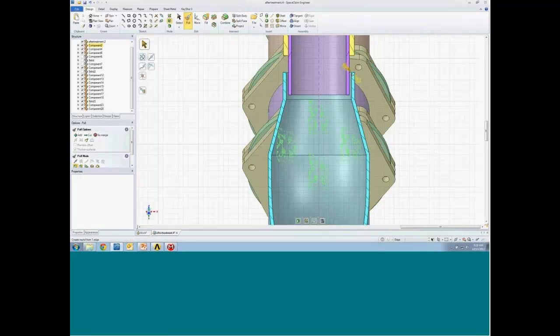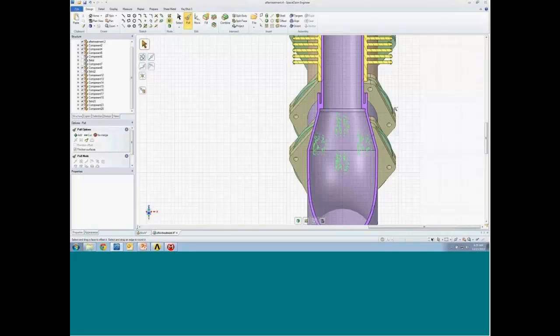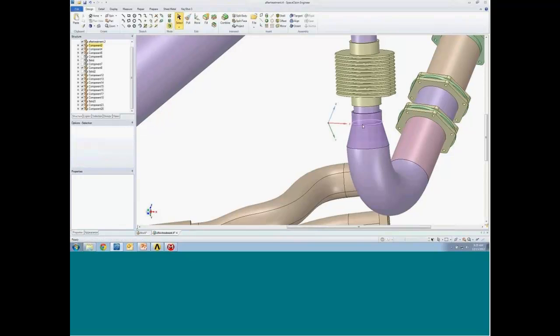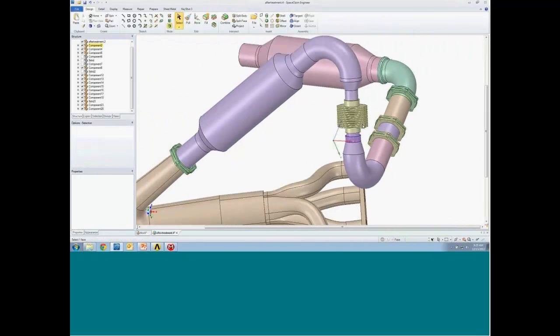Instead of pulling one body into another, I may elect to make a brand new surface. So again, even in this cross-section mode, I can start creating geometry. I'm making a new surface, a ring, namely. Pulling on that will make the definite interference between the two bodies and merge them together. And you're probably not concerned with the tiny geometry around the edges like that, and that could very well be adequate. The reason that there's some openings here is maybe a translation didn't come through correctly, or maybe the engineer that gave you this model neglected to put certain components in there for whatever reason. But you have the power to go correct these minor problems, which could be major problems, in SpaceClaim.